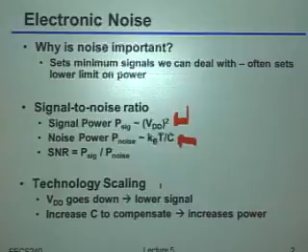And of course, as we saw before, the current you had to spend in your amplifier was directly related to the capacitance, because the higher the capacitance, the more current you needed to support a certain gain bandwidth. Now, as we'll spend a lot of time talking about in a second, this signal-to-noise ratio is really specified in terms of variance, meaning you're not dealing with a voltage over a voltage; you're dealing with a voltage squared over a voltage squared.